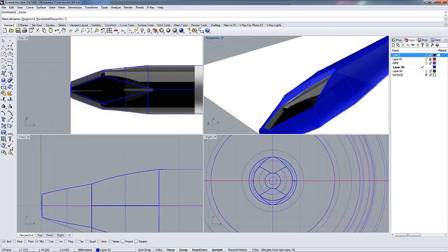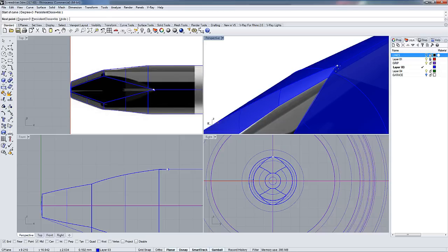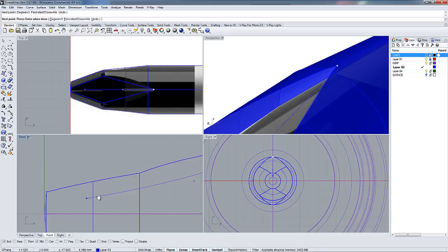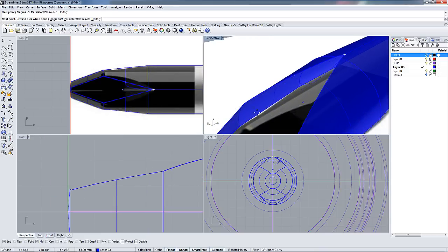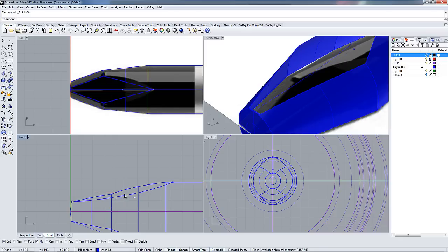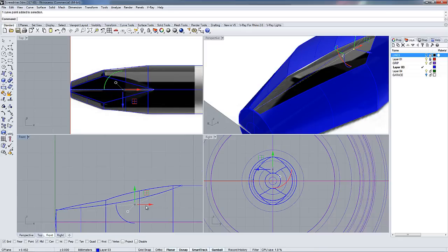and you can again select the end, and we use one control point at the almost middle of the end and press F10, and there is a slope something like this in the end of the screwdriver, so maybe we move it a little bit more.